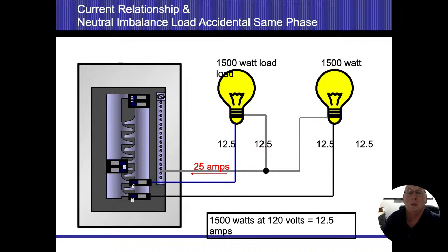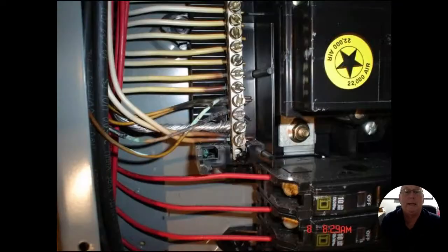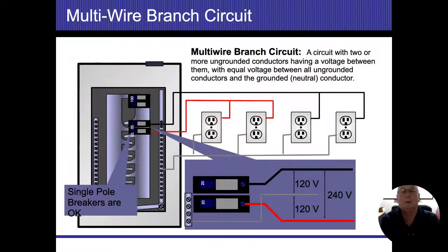and you're going to end up having 25 amps. If you have a neutral wire that you see heated up, chances are, and sometimes when you look at these panels it's hard to tell what goes where, when, and how, but there's a pretty good chance one of two things is happening. Either it was a shared neutral circuit, and they got the breakers on the same phase, so they're not on different phases coming in there, or I had a loose connection. That happens when we start double tapping and triple tapping underneath that neutral bus bar, and that starts creating resistance. Anyway, my neutrals are heating up, and these connections are burning, and it actually started a fire, a small fire, but a fire nonetheless inside that panel. Another multi-wire circuit.